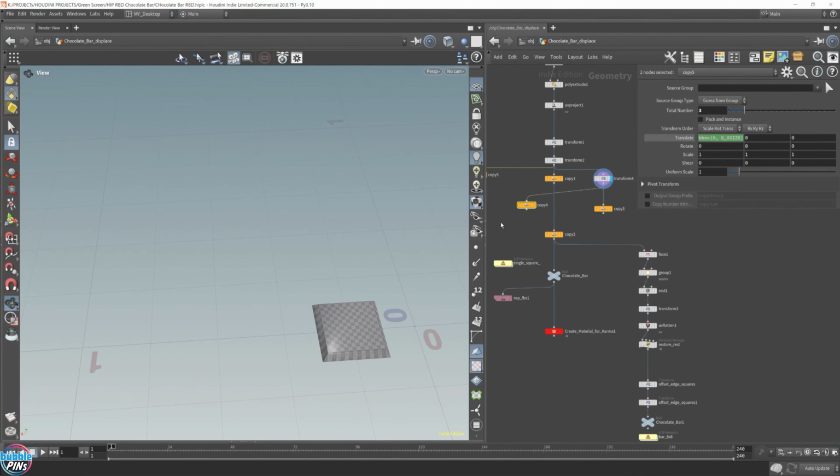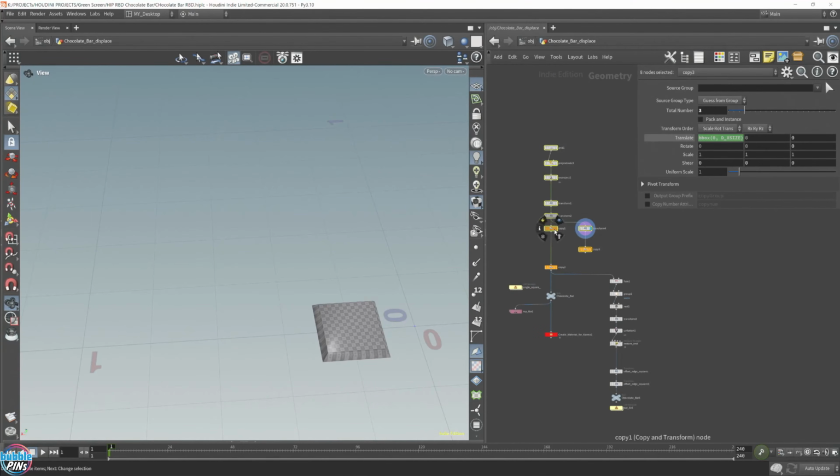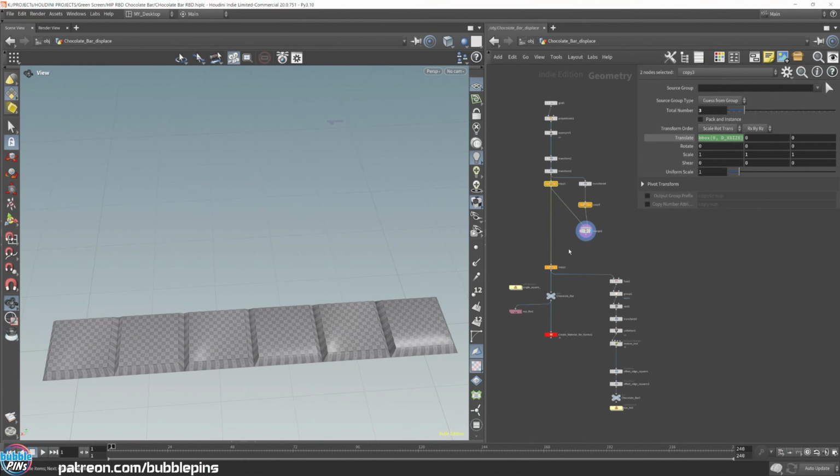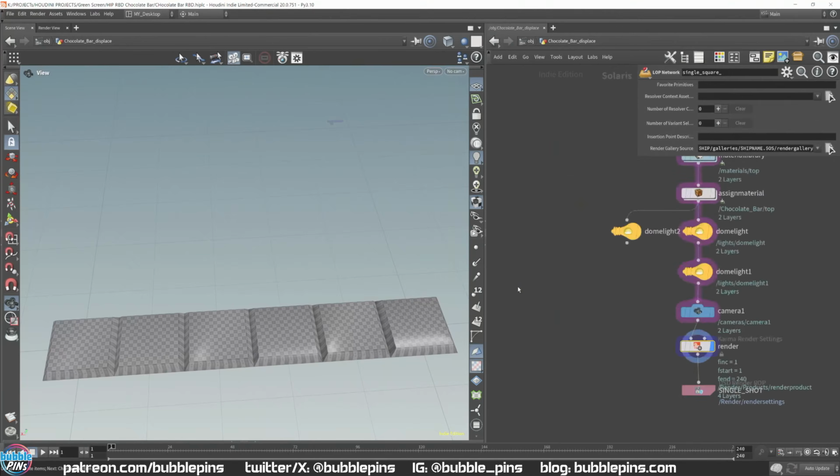Oh, sorry. I was trying to merge this. Alt. So select two nodes, hold down Alt and drag it. Sorry, let me just move it up. Select, hold down Alt, drag it out. You'll get a merge. So that shortcut is very handy. Now I'm just going to replace it with this. I'm just going to see how it looks.